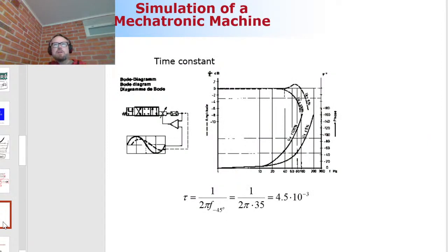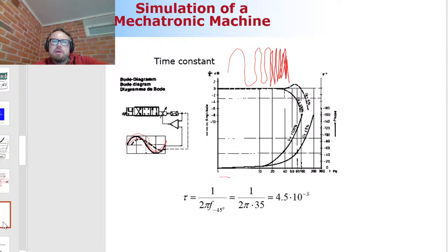This Bode diagram is made exactly like I mentioned earlier. So you're controlling the spool position using a sine function. The first assigned frequency is very low, and then it starts to increase like that. This tells you what happens when you increase the frequency.